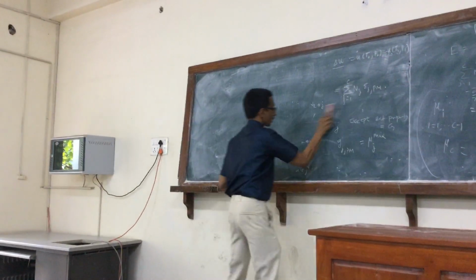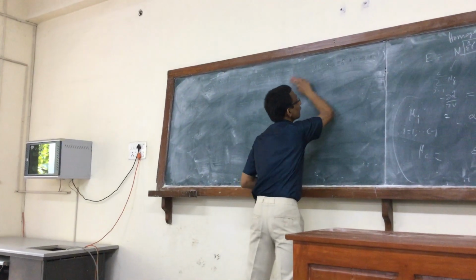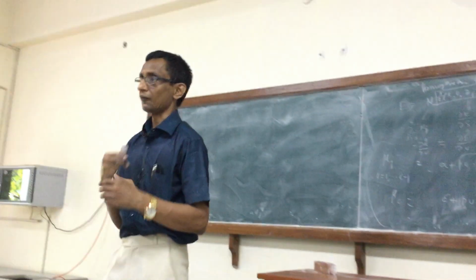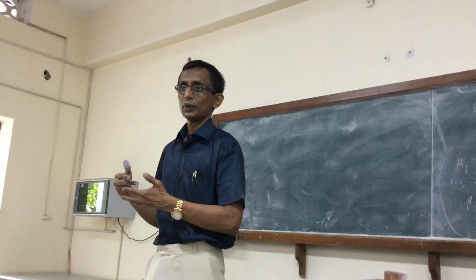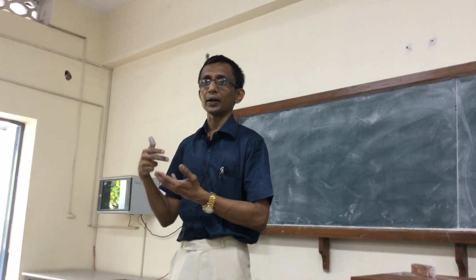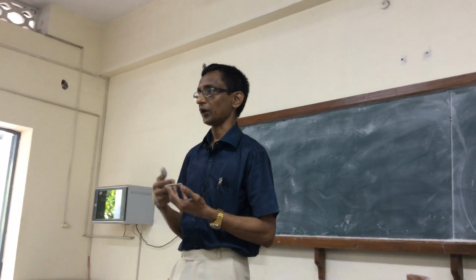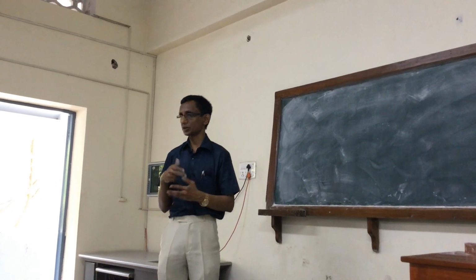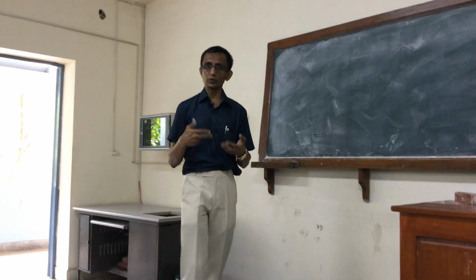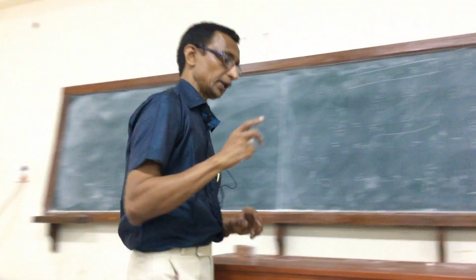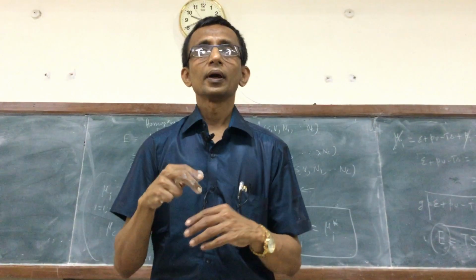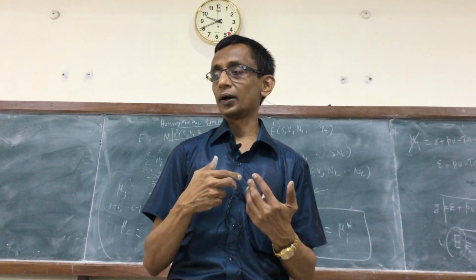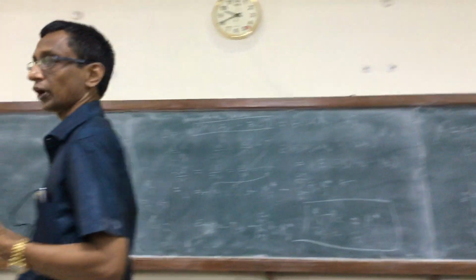So for that, we will restrict ourselves again to gas mixtures, because there also we said we will be having phase change. We have to be very careful in adding or subtracting the changes due to phase change. So we focus on the gas phase, and there we found the departure function serves a useful purpose, because by using the departure function we could relate the changes in properties by using the ideal gas specific heats into the picture, because those are readily available.